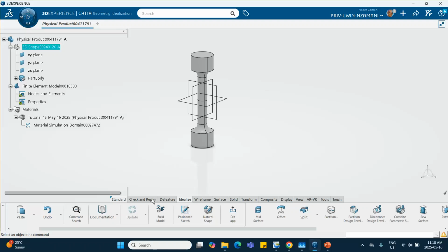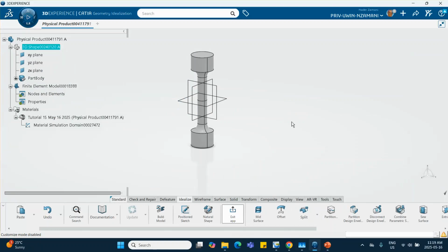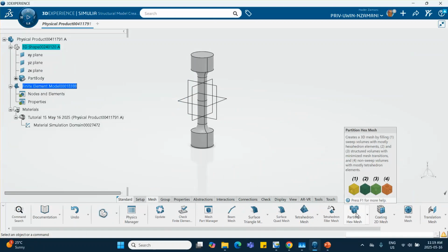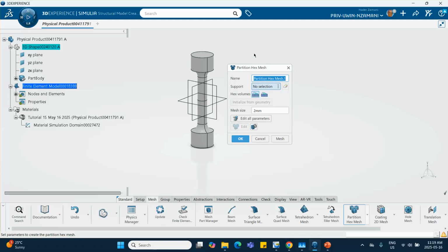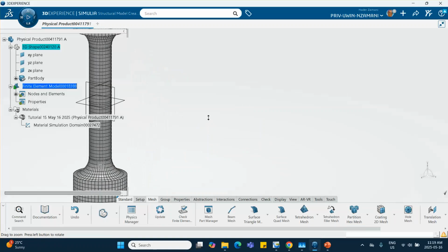Okay, so we have to exit this. Notice that this is what it's saying. Exit. All right, now we go to measure. We want to do a partition mesh. You select the part, it turns yellow. Now in the ABAQUS implementation of this problem, it became green, but that's okay. And we put down mesh size 2 millimeter and mesh it. There. Let me say okay.